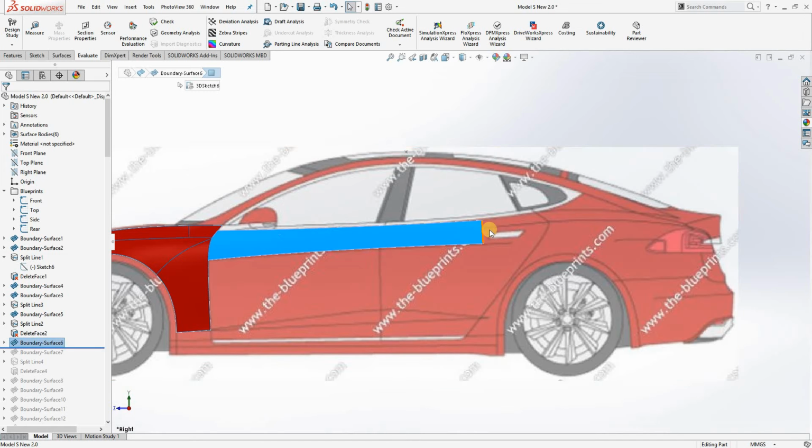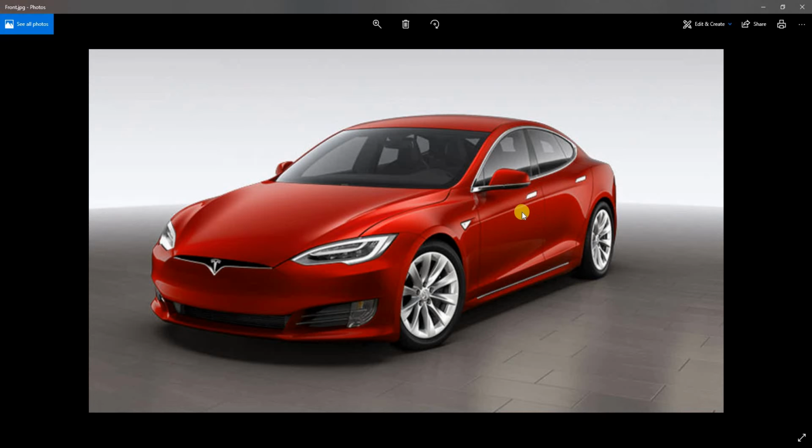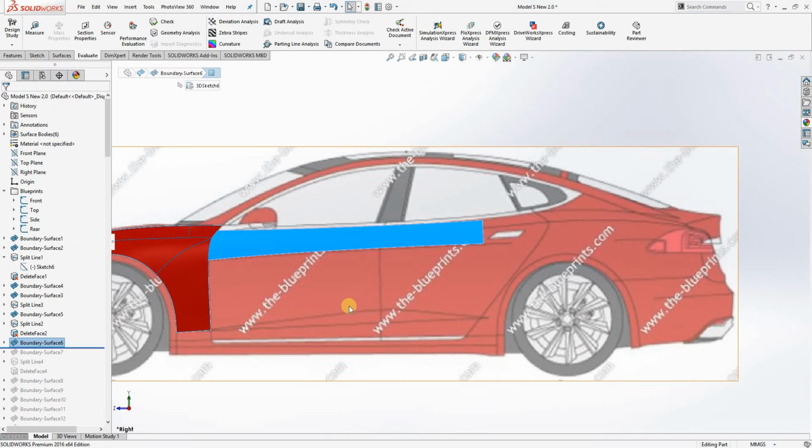The reason I decided to end it here just before this second door handle was because I can see a kink running along the side of the car which ends just about in that region just before the second door handle, and then a bit above that is another kink which starts. So if there are kinks in surfaces, as a general rule, they're good boundary sections to model your individual surfaces off.